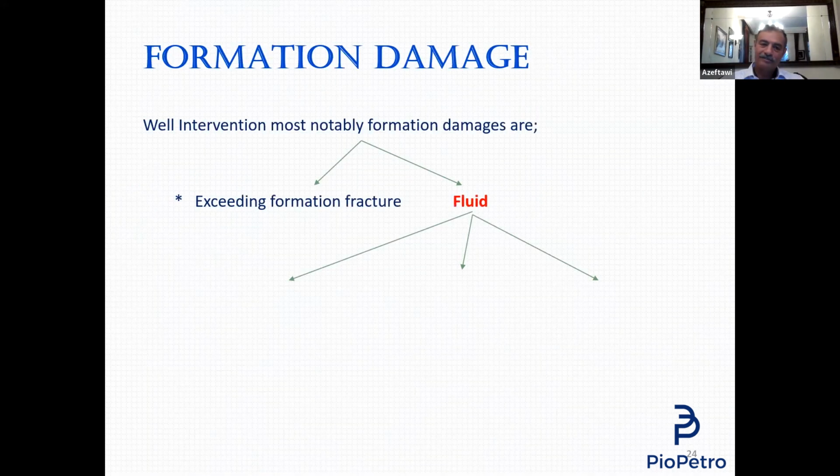When I say pressure, I mean exceeding the formation fracture pressure. If the formation fracture pressure is 3,000 and you apply 6,000 to this formation, you break it. You damage it. So people ask me, break a formation? Is it a glass to break? No, it's not glass. But if some of you don't know what a formation is, the content of the formation, if we go deep in the well and have a microscope to see what it is, is sand.